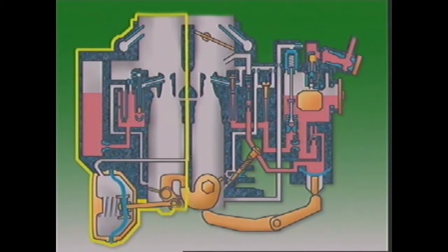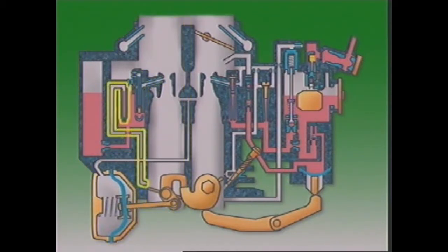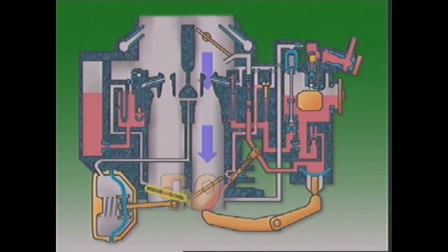The other barrel, the secondary side, supplies extra mixture but only at high speed or full throttle. It normally has a main metering system and a non-adjustable idling system. The primary side has a choke for cold starting. When the engine is being started, the throttle on the secondary side is already closed, so a choke isn't needed.